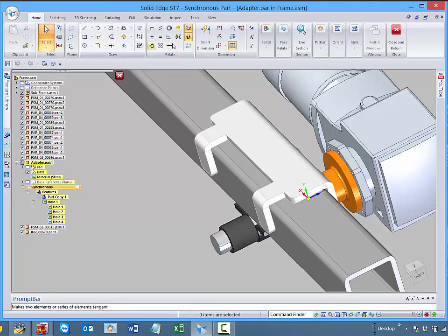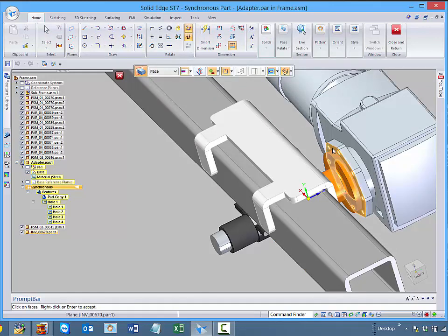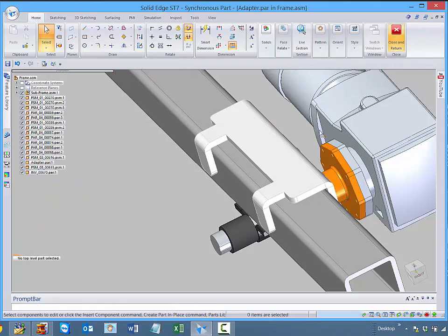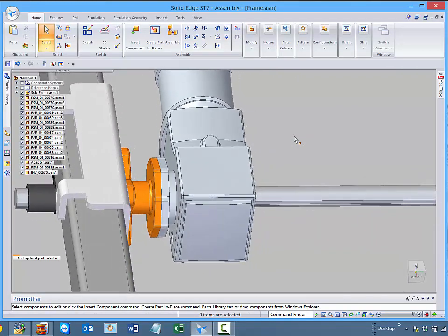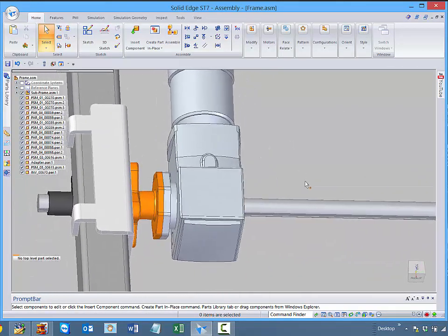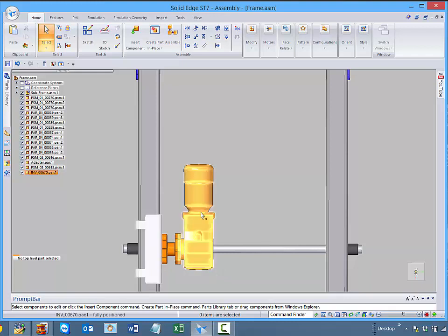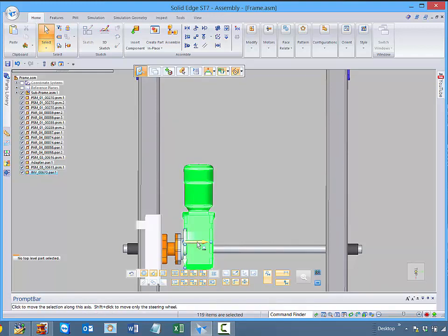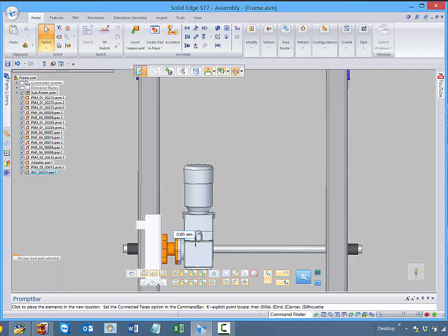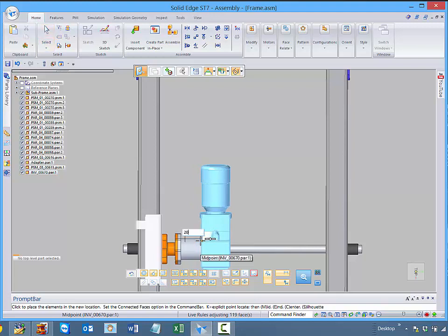Let's show our assembly, and all we want to do is just utilize that geometry there to rebuild our flange. Done nice and quick. Let's close out, and now we have an ideal situation where we can match those up. One of the things that we possibly will struggle with is the size for the fittings. So let's just change our selection mode, and what we can do is we can do a fence selection and just increase that throat size directly from the assembly. Let's just increase that by 20 mil.